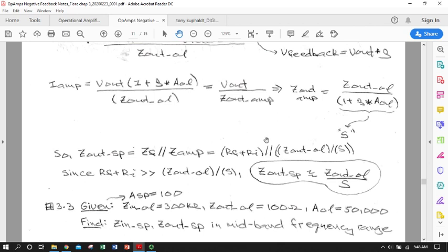Okay, in practice, most people who design operational amplifiers design them to have a fairly low output impedance. That gives you better signal amplification, less distortion, less power usage, because you're outputting your amplified signal, so you don't want a big resistor there dropping it all out.